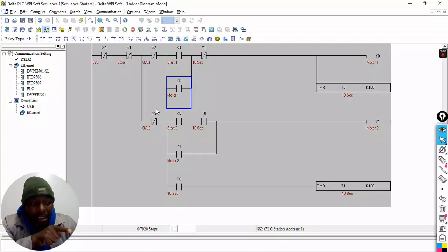this text here, what does it mean? What you understand it to mean happens if I try to start the second motor after 20 seconds. That is another difference that you need to deal with here. As we've programmed now, you cannot start this motor after 21 seconds. But the language says I should be able to start the second motor after 21 seconds, as long as the other motor has started and run for 10 seconds. Whether it's a further 10 seconds, there's no restriction to say that after a further 10 seconds, when this one has stopped, the other one cannot start.